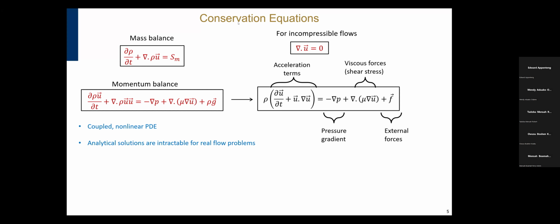How is your mesh? Well, there are no actual definitions of a good mesh, but the first thing is that your mesh should be appealing to the eye. When you look at the transitions, they should be relatively smooth. If you have a relatively coarse mesh and you are not careful, you would get divergence. So that is something you have to really take care of. Your mesh is really important.